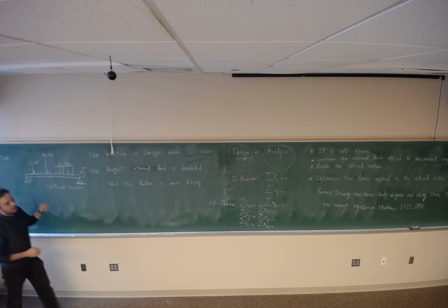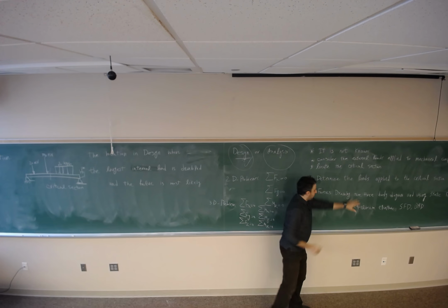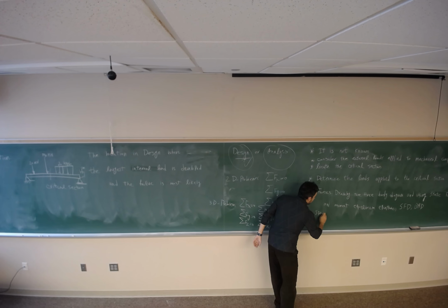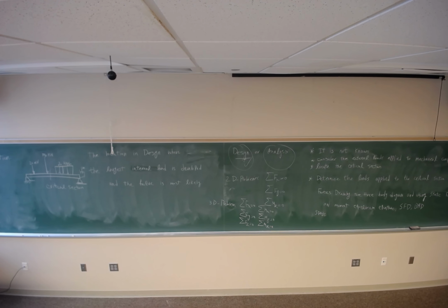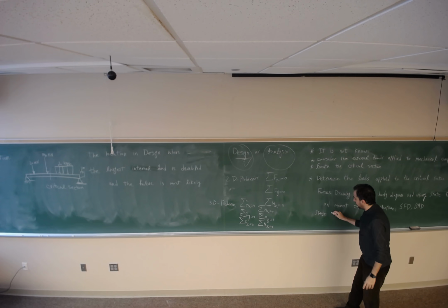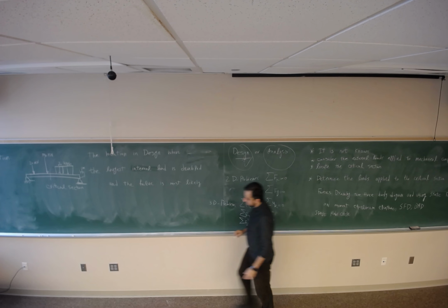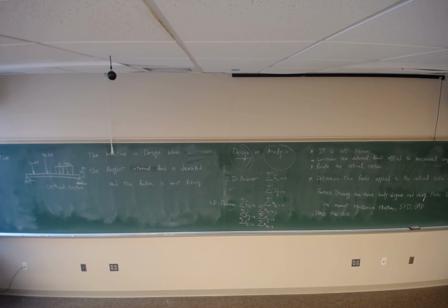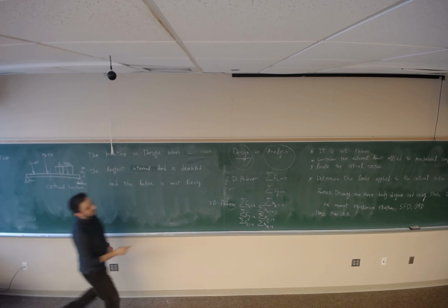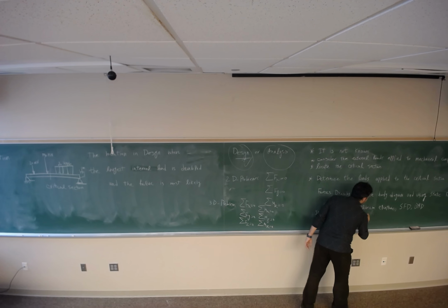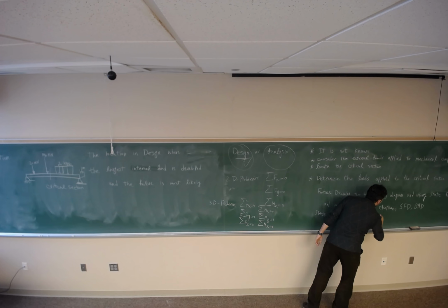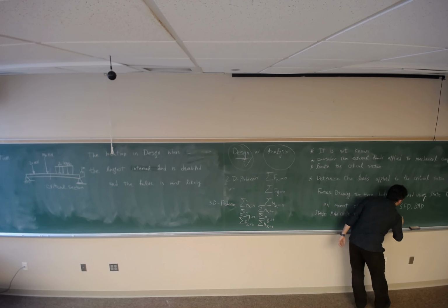So after you figure out the forces, you go to the stress. You can calculate the stress because you know what the force would be. Now it's time to calculate the stress applied to the critical section. Then, after you calculate the stress, you apply the Mohr circle to finish the analysis. You may remember that by using the Mohr circle, we are going to find the principal normal stresses. We will go through them, but just.